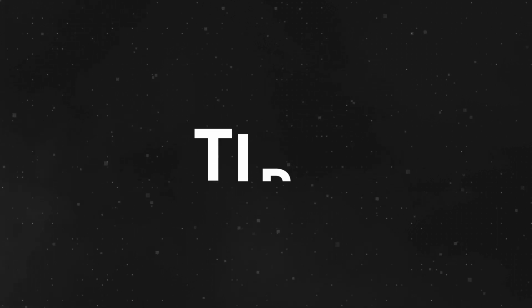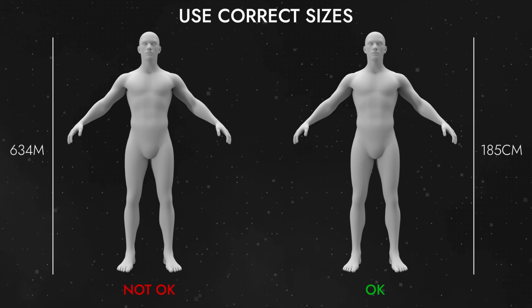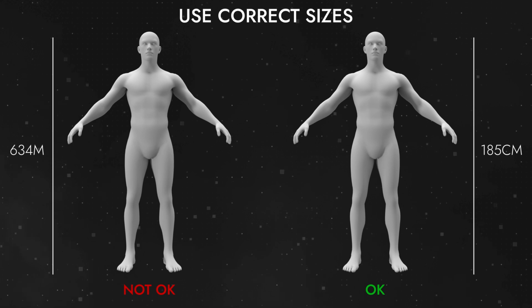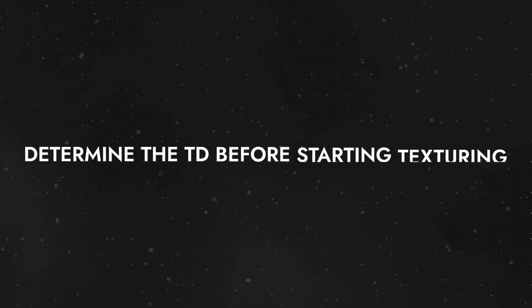And now I would like to give you some tips for working with texel density. You should always work with correct sizes. Besides helping you work properly with texel density, it's also important for rendering, and especially for physics calculations or game engines. Before starting texturing, determine the texel density. Typically, it's only selected once before starting work, and set for the entire project.